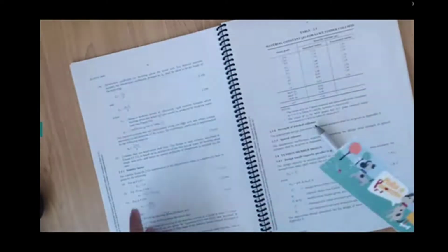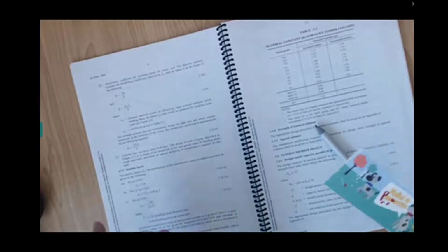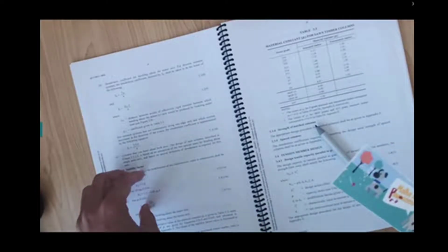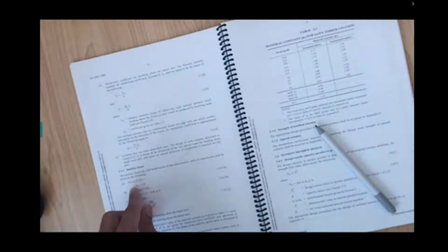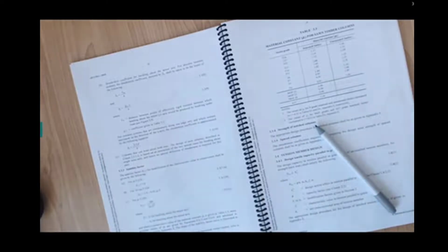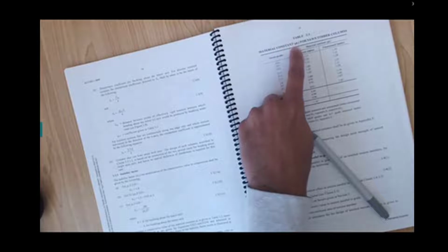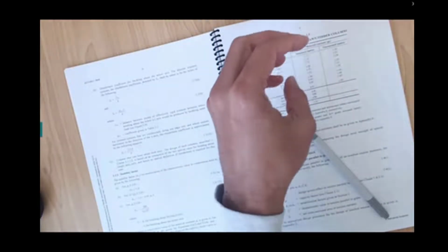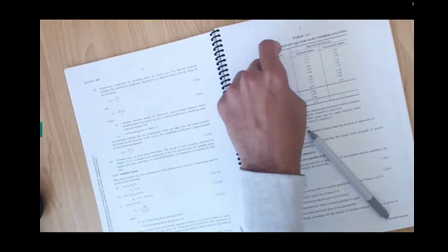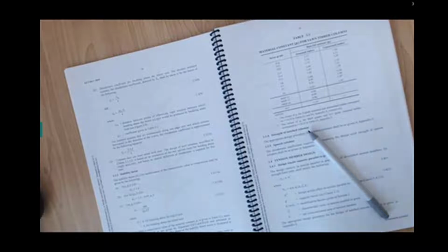So by looking at the columns, you can't just say this is a short column, intermediate column, or long column. It has a consideration of how the restraints and other factors are affecting it. So it has this multiplication, rho C times S. Rho C is quite simple to calculate, and it is called the material constant. The material constant takes into account the creep, shrinkage, and the grade. What is the grade you have? You have seasoned timber and unseasoned timber in that case.